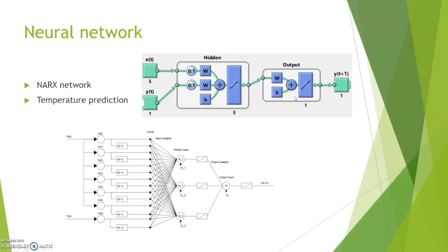The neural network we ended up implementing is a NARX network. It has a very good structure for predicting time series data, as it mixes the inputs, which in this case are the other measurements, and the output of some fuzzy logic controllers with the inputs, which in this case is temperature. It then runs these through weights and biases and into neurons. There are 3 neurons in the hidden layer, as indicated here, where all of these have tan sigmoid activation function.